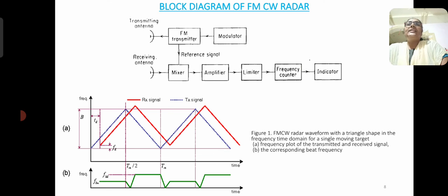In the above, the target was assumed to be stationary. If not, a Doppler frequency shift will be superimposed on the FM range beat note and erroneous range measurement results. Here, f0 is the frequency with which the radar transmitter signal is transmitted. In the FM radar, the frequency of echo signals is shifted up and down. When the target is moving approaching, the Doppler fd will be greater than the range fr. It increases the portion of FM cycles. The beat frequency fb up will be equal to fr minus fd.